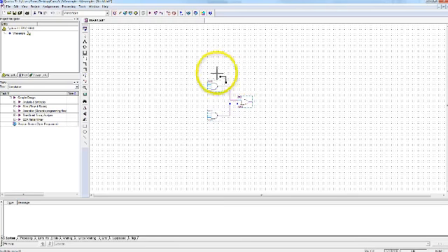If I make a missed connection somewhere, so I'm going to delete that, you'll get a little X, and that X is going to tell you that you've missed a connection. You need to go back and fix that. So in this case, I'm going to drag over, and if I drag too far, you can see again I have this little missed connection here. You need to be aware of those and make sure you don't have any stray wires floating around. So I'm just going to delete that, and again, there we go. That looks good. Now I need to connect my inputs and outputs.